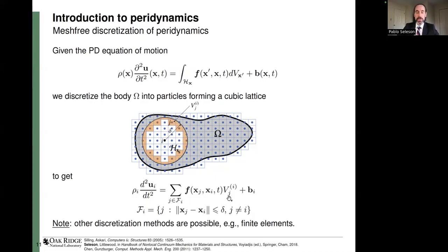It's a Riemann type discretization, where the weights initially are taken as the full volume of the cell, characterizing each node in blue, but there are methods, enhanced quadratures, to improve the discretization. Now, overall, once you compute, what we would have for your simulations is a set of particles or computational nodes, where each node I interacts with a surrounding family of particles J, so that all points J are within the neighborhood of I. However, we can do other discretization methods, for example finite elements, but we are going to show now some of the simulations with this particle-based discretization.